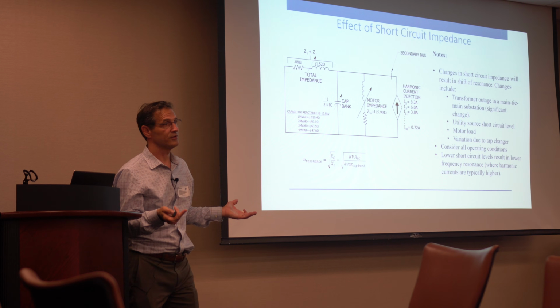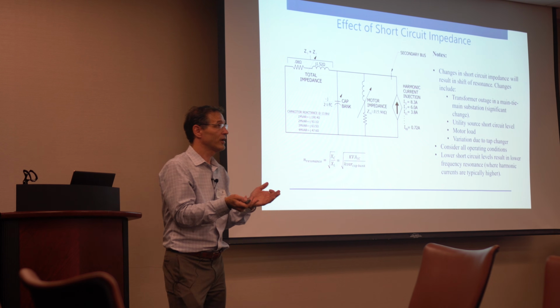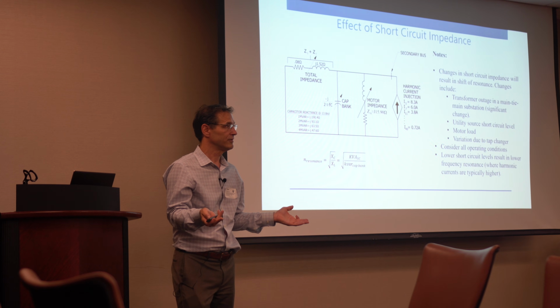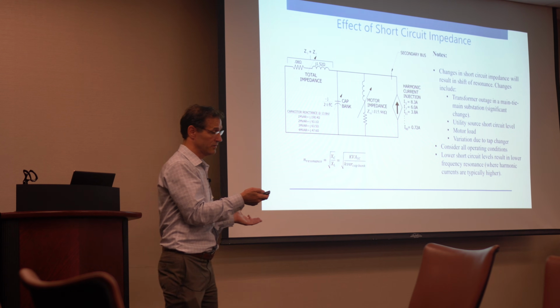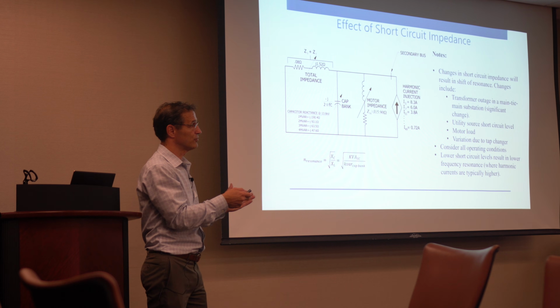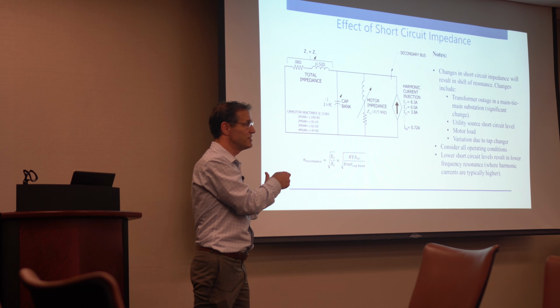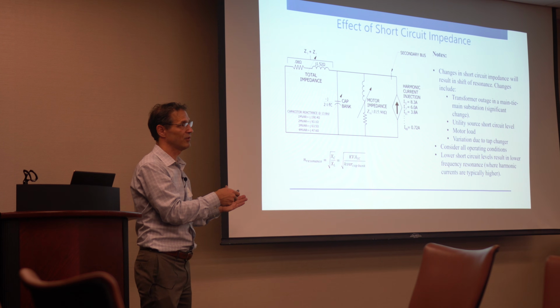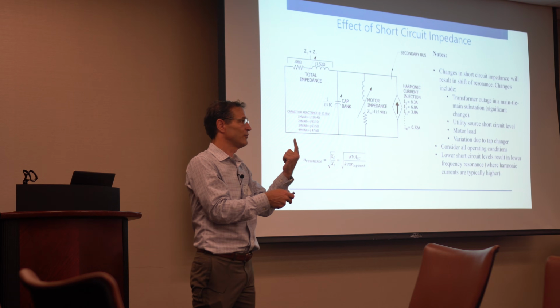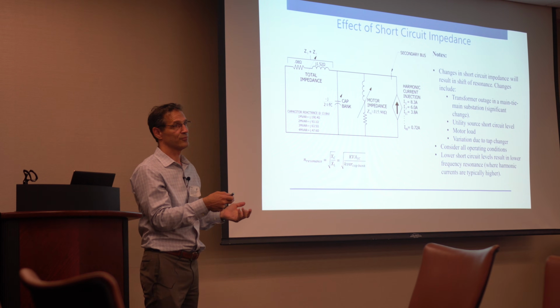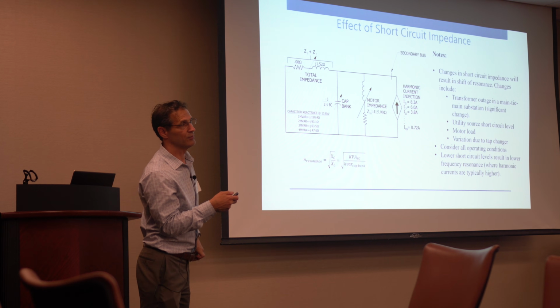You have a drive supplier who says, I'm 519 compliant. Technically speaking, the system's not 519 compliant. The drive might be compliant, but you add a capacitor to the network and it's not compliant anymore, because you just multiplied that 1 little amp by 80 times, and that becomes a problem.